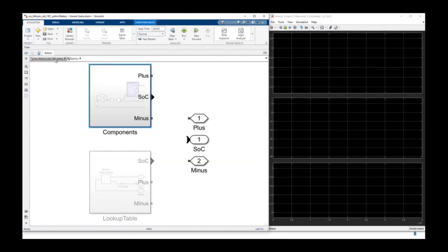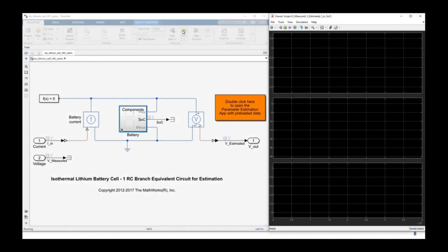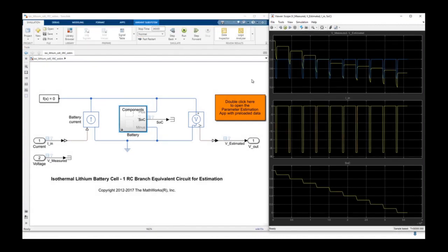Now let's simulate this and have a look at the result. On the right-hand side, you can see the input current, made of these negative pulses that take energy out of the battery. That's exactly what we want. We have 10 of these pulses. At the bottom you can see the state of charge of the battery. At the beginning, the battery was full, and at the end, after we have taken current out of the battery several times, the battery is empty at 0. So that's perfectly fine.